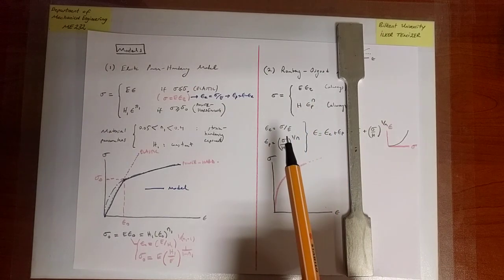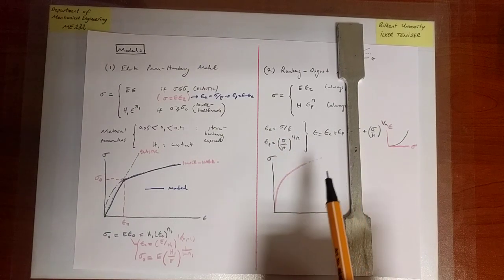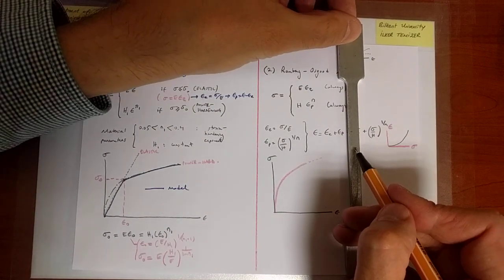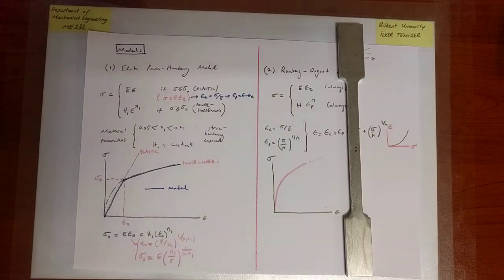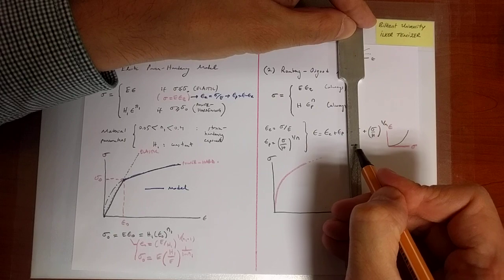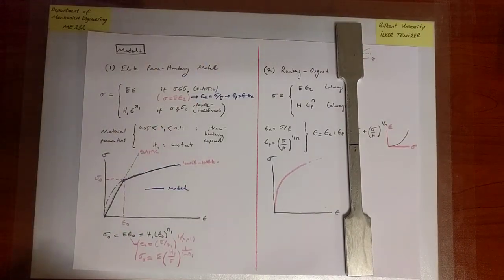But that amount of plastic strain is there, however, it's not appreciable. The plastic strain starts to become appreciable when plasticity occurs not only in the vicinity of the imperfections, but across the whole interface, and that's what I'm drawing with blue here.